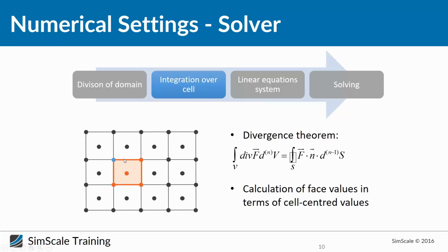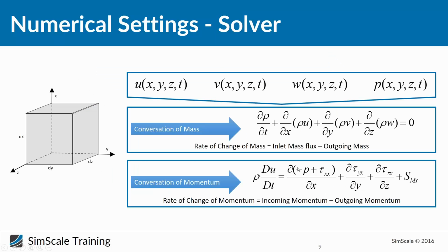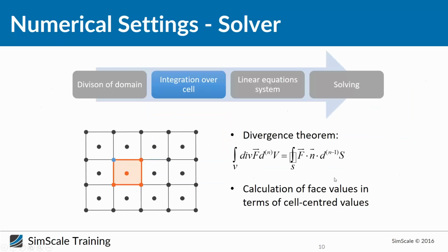And this is, I think, the most important thing when we talk about CFD: even if we create the mesh, we still have these differential equations which we cannot solve, these 2 equations, the Navier-Stokes equations. So what can we do? There is something which can help us, called the Gauss divergence theorem. It says something very easy: it relates the flux of a vector field through a surface to the behavior of the vector field inside. So it allows us to calculate, from the flux through the boundaries, the flux change inside the cell.